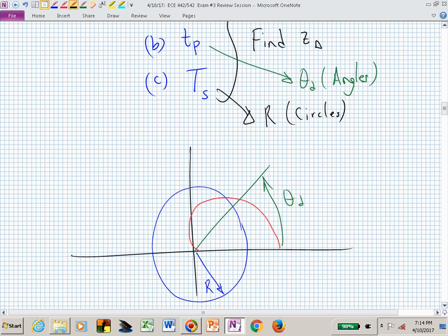But here's how you now would want to fit those into desirable locations for your closed loop poles. Given a wedge, which is an angle, theta sub d, that's the peak time. Given a settling time spec, which are the circles, and given percent overshoot, which are these logarithmic spirals or hearts. And what's a default way to be thinking of this? A lot of times, reducing the radius is the one that makes you meet most of these specifications more easily or more effectively.